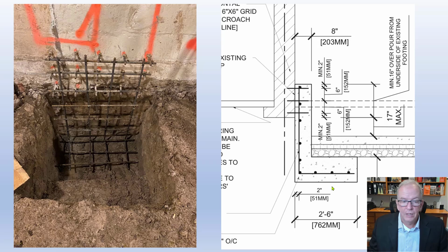So looking at this, you could take a minute yourself. It's pretty quick, if you're used to looking at drawings. And if you're not, by the way, I've got a playlist of reading construction drawings that could be helpful. So if you click my face and you go to the playlist, you should be able to see the one on print reading. And so in this case, these are your rebar, and you can count pretty clearly 1, 2, 3, 4 cross members of the rebar. And here I only see 3. As well, it's not coming out near far enough.